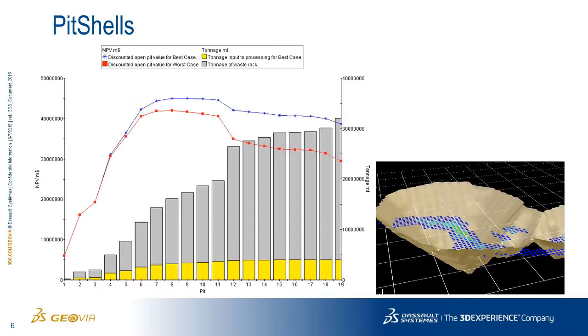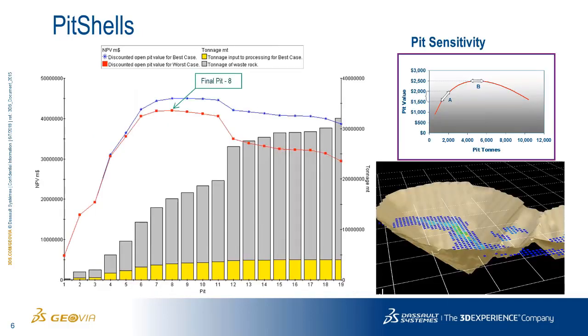So just following up visually on those 2 phases, obviously the pit shell node, most people are pretty familiar with. We have our pit by pit graphs, we have our breakdown, our nested shells. Can take a look at each phase and do some examination, do some sensitivity, looking at it, is it operationally sound, using some of the other Whittle modules like mining width and things like that to make them operationally sound. But in the end, those form the geometric basis for our schedule.